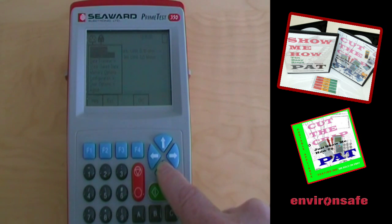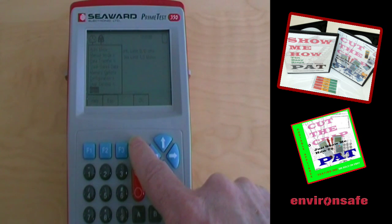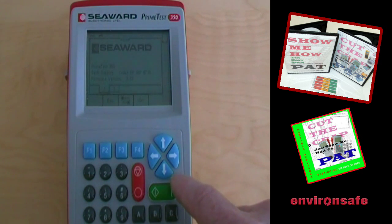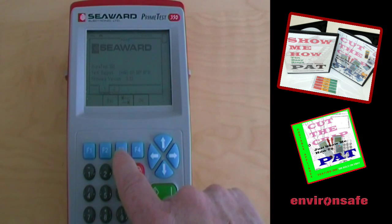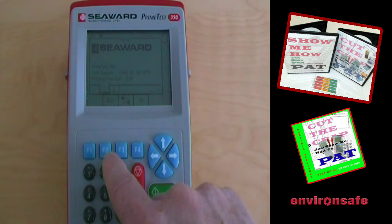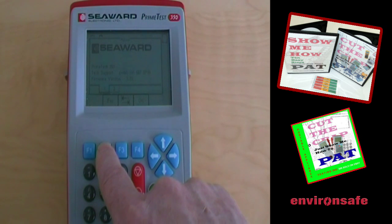Using the down arrows to scroll to about. F4 to choose, and this gives you information about the Primetest 350 and the firmware version, which this one is 3.33. If you want to select that, press F4, F3 if you want to navigate, and F2 to escape, which is what we are going to do.